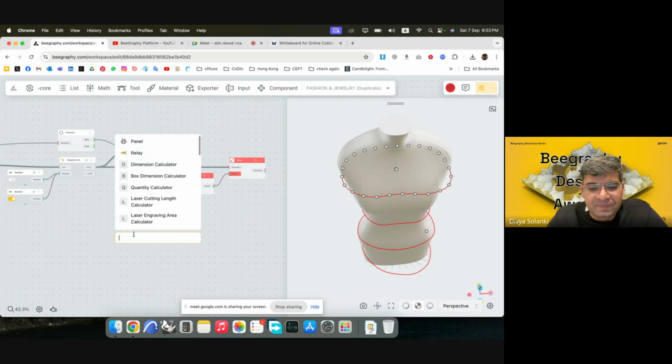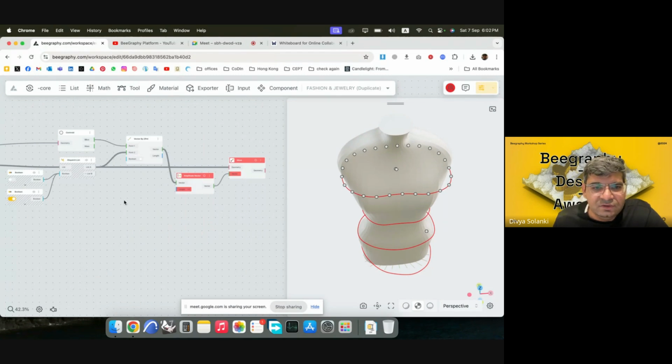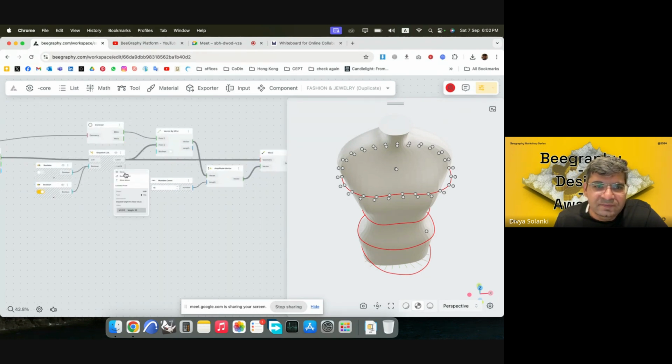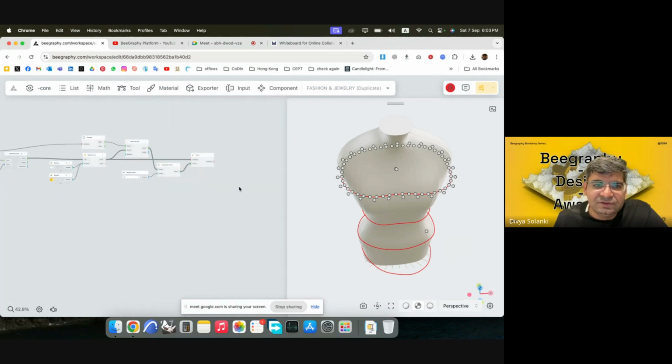So first thing we can do is try a simple one. I'll just move these points by a constant of 15. You can see these points have been moved out. And then we have the other set of points as well, these ones, and we would want to develop a polyline going from one list to the other.